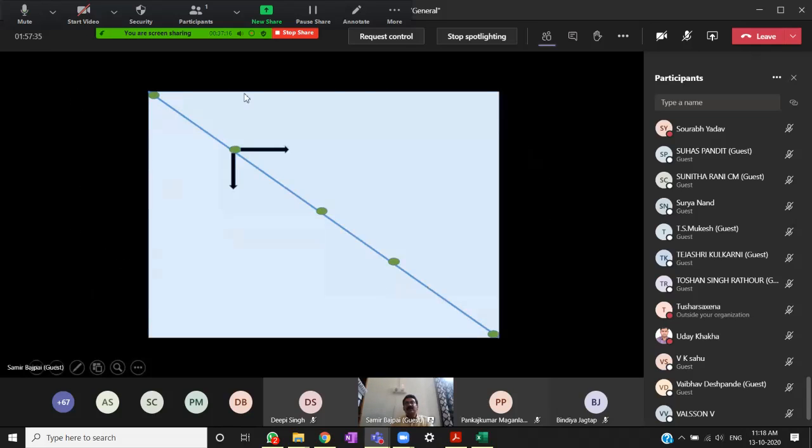Typically we can understand sedimentation by this: a particle is entering the settling tank, there is a water flow, and water is coming with a certain velocity inside this settling tank, and this particle will be acted upon by two forces. One is the horizontal inertia, the flow inertia of the water, and the weight of the particle. Apart from this, there will be another two forces, drag force acting on the particle upwards, and buoyancy of the water, which will be restricting the downfall of the particle. Based on this, the particle will ultimately achieve what is known as terminal settling velocity or equilibrium settling velocity.